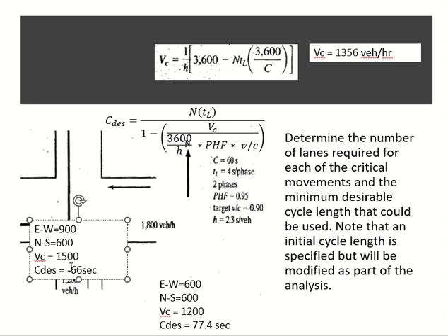Minus 66. So minus means what? Not acceptable. So what can I do to change this minus into something positive? Change the V by C ratio like we did last time. Not the VC, V by C ratio. Clear? So these 2 examples show you how you can play with the geometry of the intersection or your design parameters to come up with a practical, acceptable value. Fair?